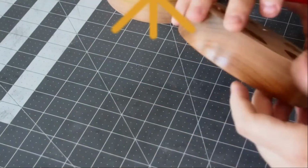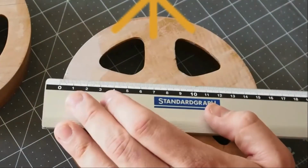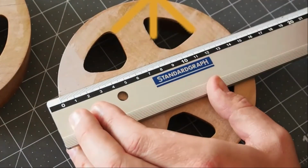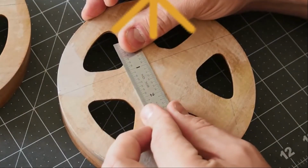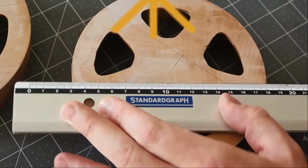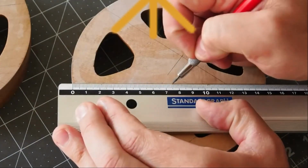To find the center of any circle, you can draw an arbitrary line across the circle. Divide the line in half and draw a perpendicular line towards the center. Do this as many times as necessary until you feel confident that you found the center.